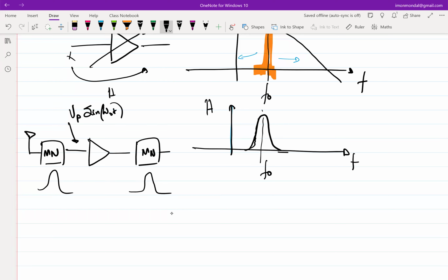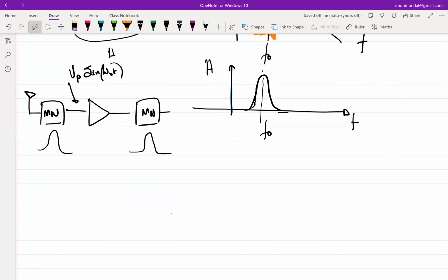And we understand from our treatment of amplifiers in other courses, these amplifiers are made up of transistors which are nonlinear, which means I can express its characteristics as V out is equal to some VDC plus A1 V in, where V in is the incremental input voltage, plus A2 V in squared, plus A3 V in cubed, and so forth.